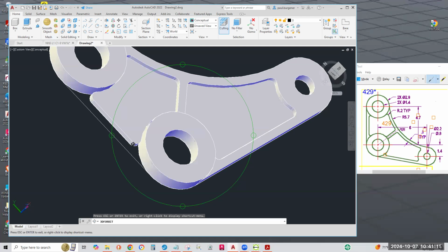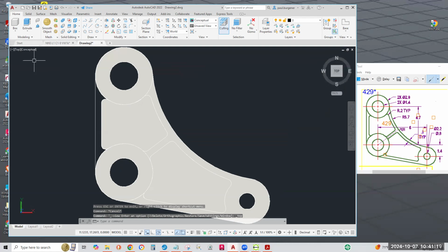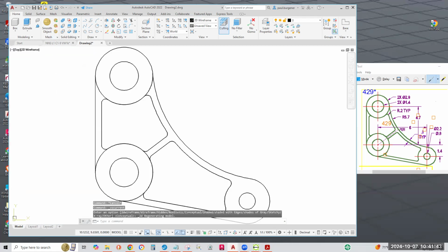All right, we'll fix that. Let's go to top view. Anytime you use an orthographic view, double check the UCS didn't change on you. There's a couple, was it UCS ortho and UCS follow, I believe, system variables. By default, the UCS changes on you when you least expect it. Let's go to 2D wireframe. Good, there's the square, so we're still in the world coordinate system.